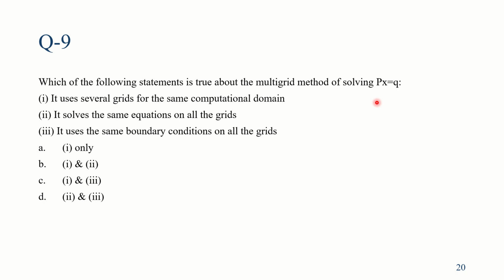Multigrid method is nothing but where we are solving the system from the finest grid to the coarsest grid, so that we can reduce or dampen out the error caused due to fluctuations. So this reduction of error would further reduce the residual. So if the residual is reduced, we can say that we are getting a proper converged solution. So what we are doing, we are solving the system in a series of grids.